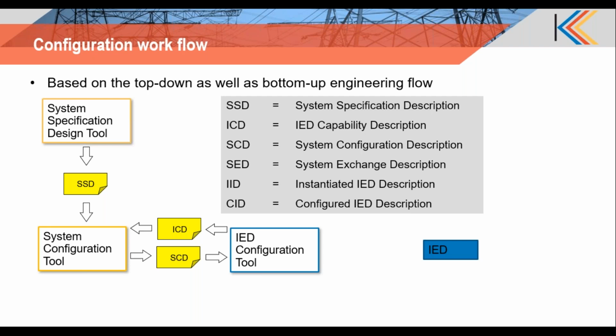The SCD, being your master configuration file, will not have that update, because the IED configuration tool is not supposed to edit any of the SCD information. Instead, it has to extract the relevant information and create the ICD. So that was one shortcoming in edition 1, and different vendors used different mechanisms. In edition 2.1 or edition 2, IEC provided a standard mechanism for addressing this issue, and that is called the IID file.